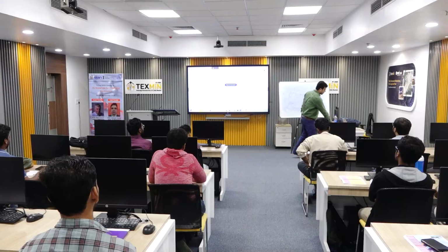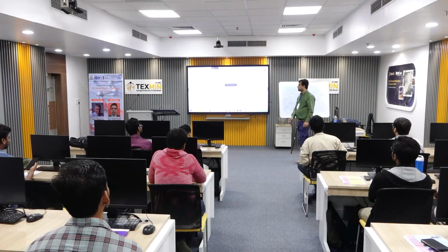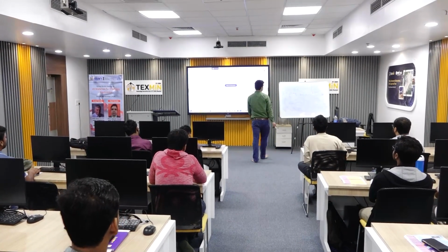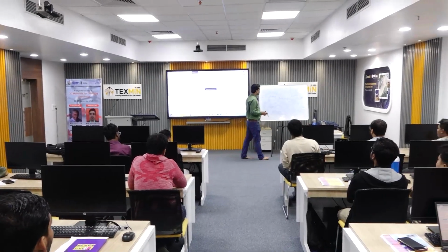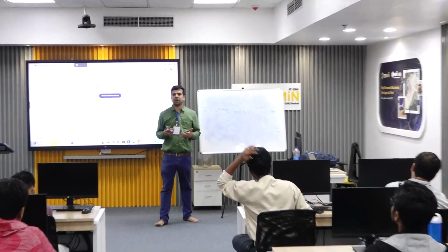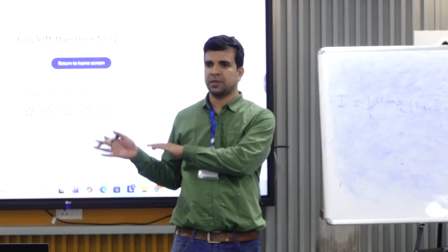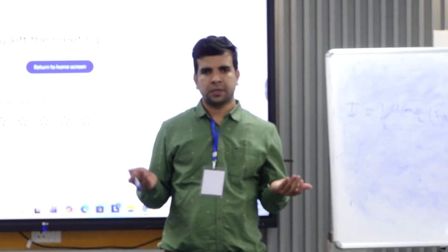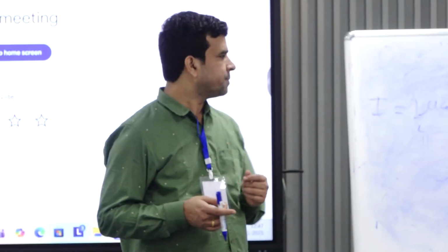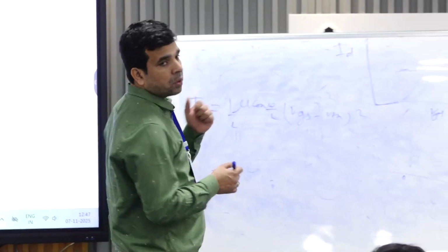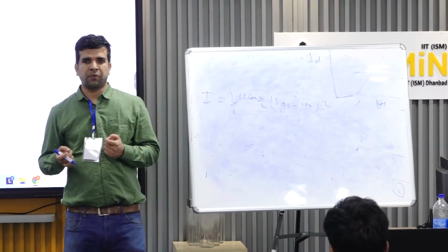Yeah, so I was discussing, again, to finish this. Basically I was saying that there are so many parameters you have to measure in characterization. One is how to find the contact resistance, another is how to find the sheet resistivity, and from a device perspective, you also have to find out the threshold voltage. If you make a transistor, you have to find out the threshold voltage.